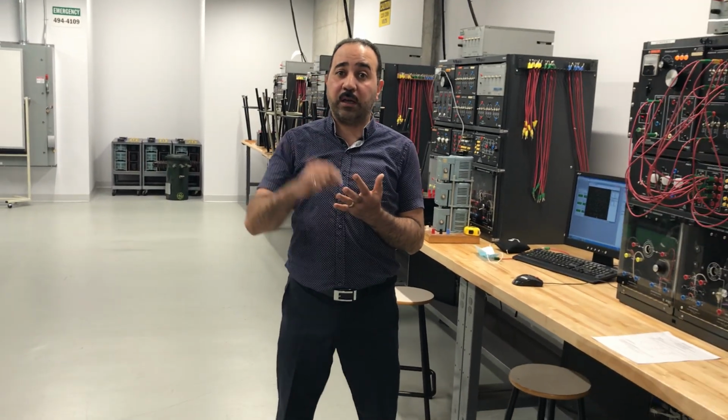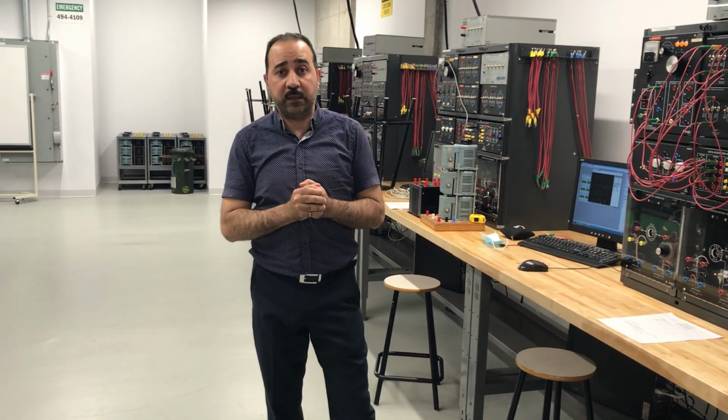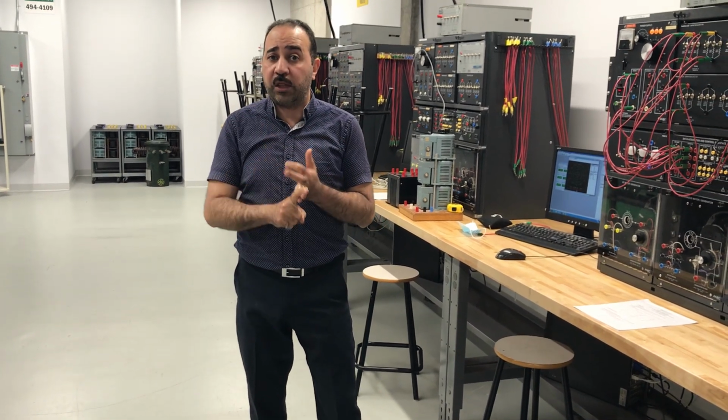This is the end of today's lab. I showed you how to measure the voltage, how to measure the currents, how to measure the power as well, and I showed you how to measure the power factor, and I showed you the relation between the waveform of the voltage and the current in case of the supply and in case of the resistive element. If you want, you can also see the relation between V and I. In case of a capacitive element, there is a phase shift, and in case of an inductive element, also there is a phase shift. This is the end of today's lab.